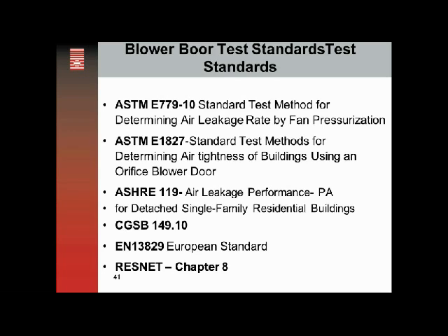If you're initially trying to do a single point test, you would move into a repeated single point test or a multi-point test. Under ResNet protocol, if you didn't do that, and that baseline range was greater than 5 pascals, you would be testing to a reduced test standard, which would hurt a HERS score. So again, get a copy of the ResNet test standards. Keep an eye on this. I think the ResNet standard, because it's a consensus standard, is a great document that's out there in the public domain, and we all should be looking at that and maybe adopting that as a potential new test standard for the international codes. Something to think about.